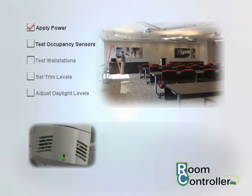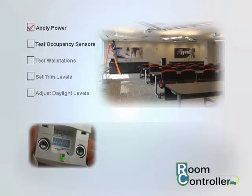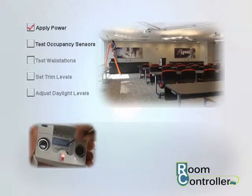After a short 2-minute power-up period, for OAC and OAWC sensors, move dip switch 10 out of its current position for 3 seconds and then back to invoke test mode. If you have 2 sensors in your room, make sure both are in test mode.